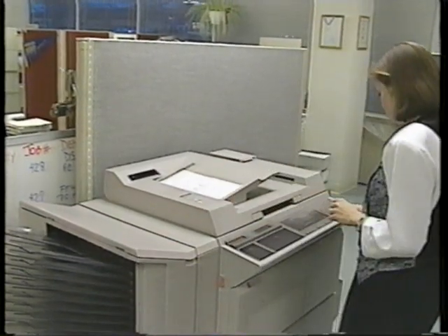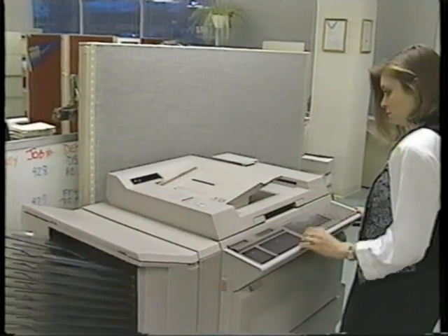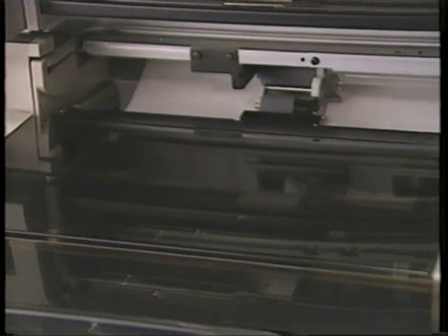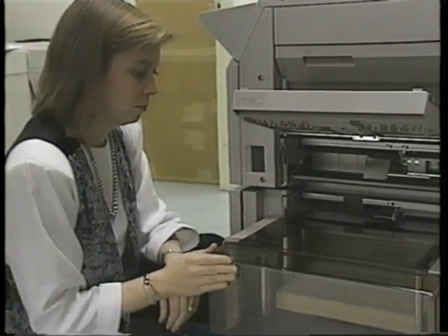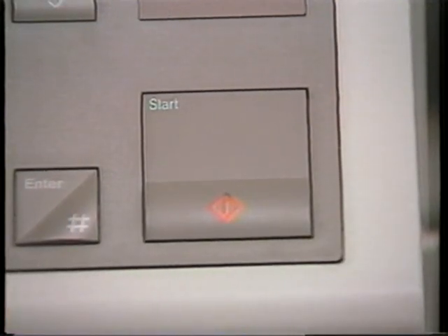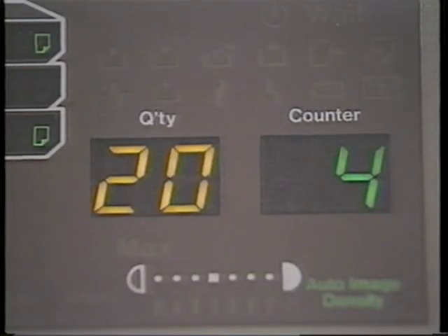Transport is the most obvious of the three. Paper has to move through the copier at the right speed and with the right timing. Paper separation is a requirement for any sheet-fed copier. Since the machine takes paper from a stack of possibly thousands of sheets, it needs a way to make sure only one sheet is fed for each copy cycle.